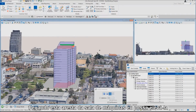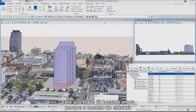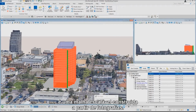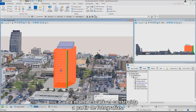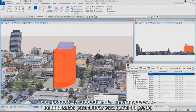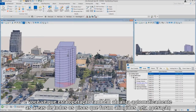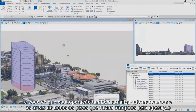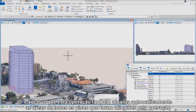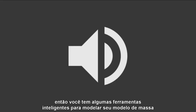If I grab up with the mechanical and be pulling it up, I could actually snap over to that other building off onto the left to match that same height, because it is the snappable, scalable 3D model from photographs. And then I can go in and do other cut and Boolean tools, or I could fillet the corner of the building, and you'll see that when I put the curve in, the floor plates automatically update, and that square footage is automatically calculated. So you just have some intelligent tools as you're modeling your massing model.